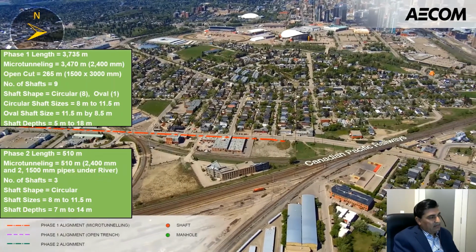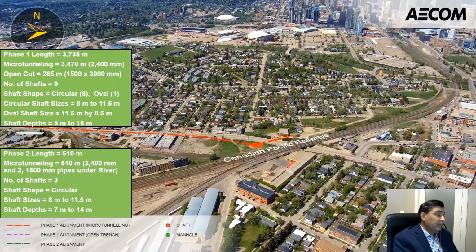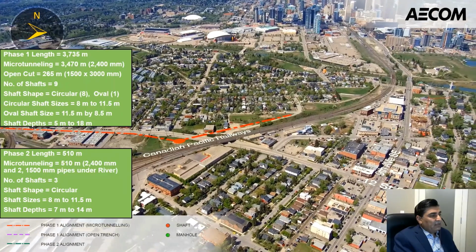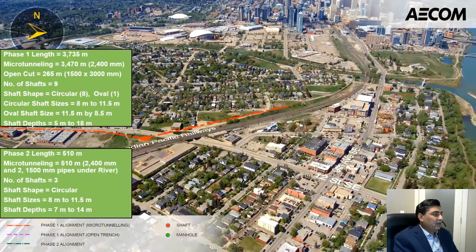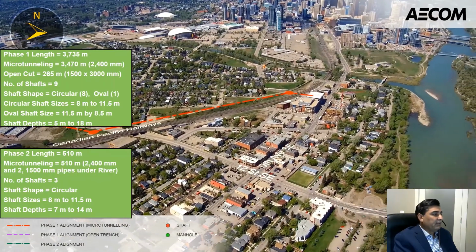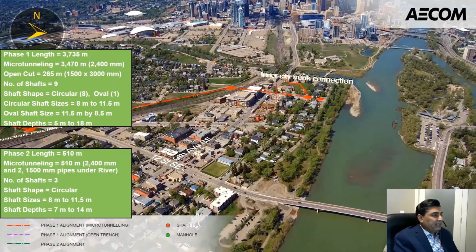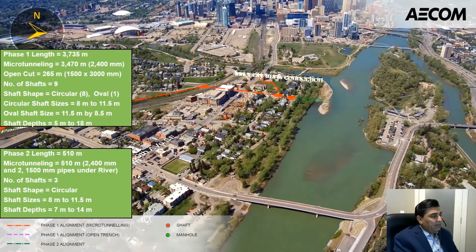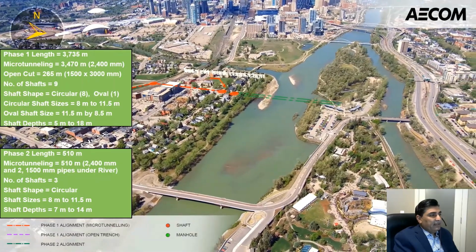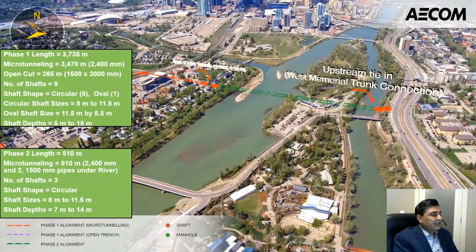Phase 2 is about 510 meters long and it is basically a bore over crossing. Microtunneling was 510 meters. It means everything in phase 2 will be done by microtunneling. The tunnel section outside river was 2400 millimeter and under river we will be using two 1500 millimeter pipes. This means that we will use two types of machines, one of size 2400 millimeter and the other of size 1500 millimeter.